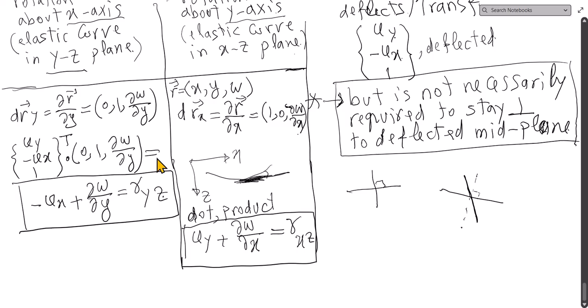So what we are saying here is that again, if this angle becomes 90, therefore the cosine 90 is 0, this gamma goes away, and then we recover our Kirchhoff plate theory, which requires that the midplane is always perpendicular to the initially perpendicular material.